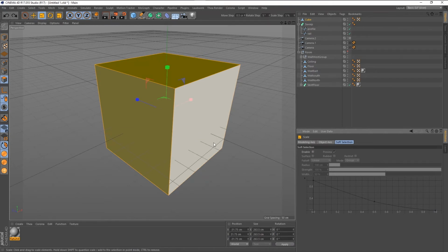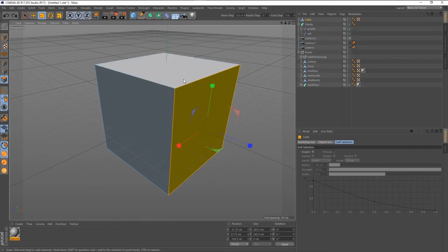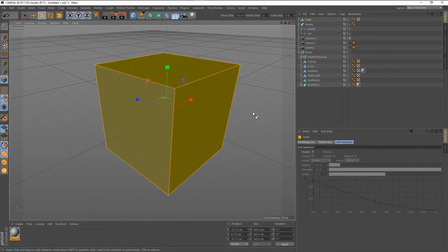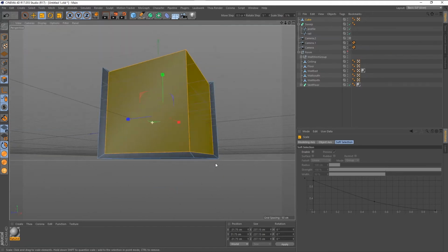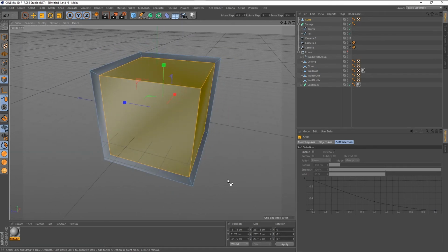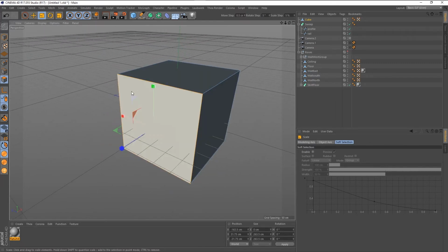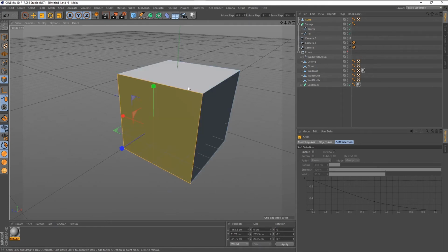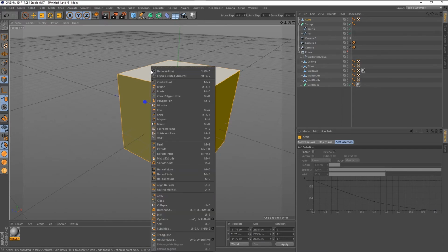Okay, so if you hold one face and you hold Control and click and drag, it doesn't inset. But if you hold three faces, it only insets the outer face like that. And apparently because it's scaling in all three directions, of course it scales it down, which actually is kind of an interesting effect. So, you know, if you want to do it, I think if you shift click on those three faces, right click, you can choose the inset.